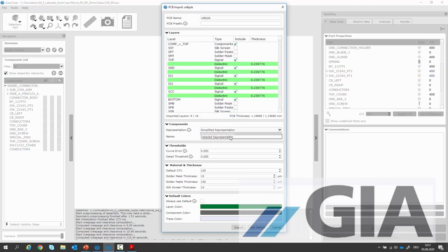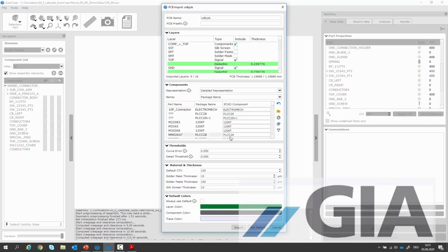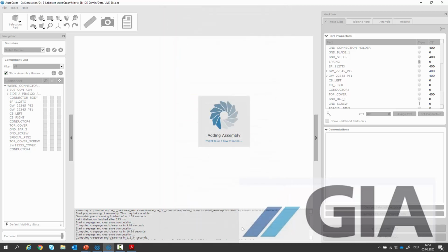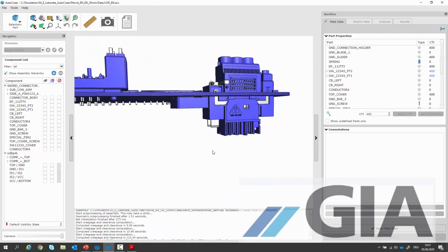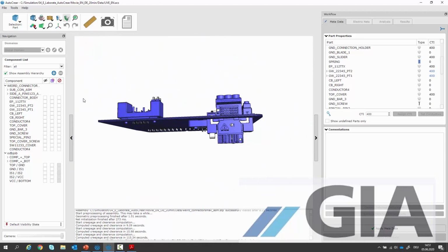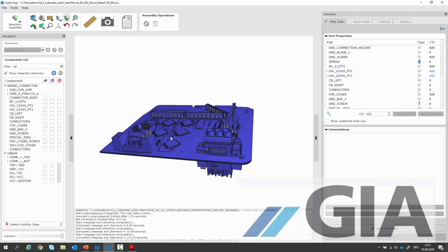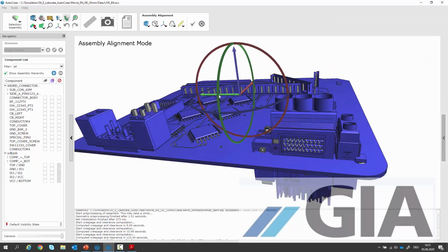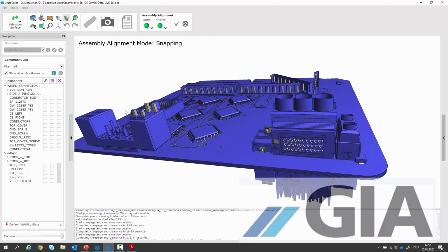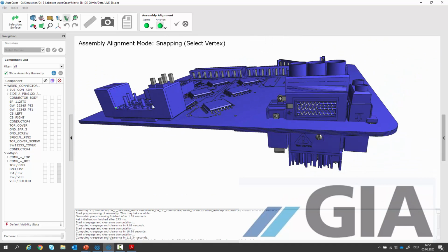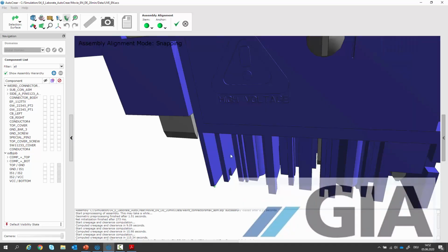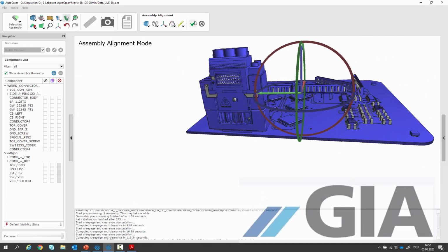create an assembly before where I'm creating a detailed representation of my components, I can import here, let's say, the very detailed shape of my PCB. Right now it's coming in. Of course, I should place it here in the right position. I'm just selecting the PCB and I'm assembling it with the help of some coincident points. Just selecting the first point, this point here has to be matched with that point here. I'm accepting it and now I have the right position.